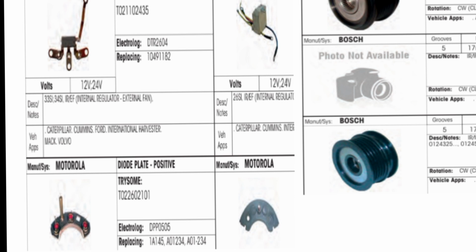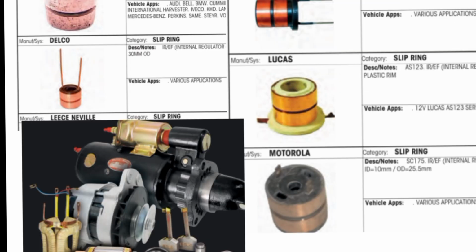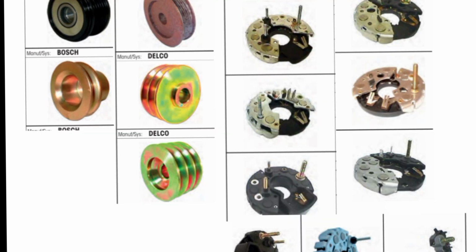Internal component: stator has 3 windings. Rotor rotates with the armature shaft. There are 2 types of winding. Rectifier converts AC to DC current. Regulator controls the output. Carbon brush used. Maintenance: check bearings, belt tension and dust entry. Common problems in alternator. Tools required for alternator repair. Testing of alternator. Checking field coil and stator. Check rectifier procedure. Check regulator procedure.